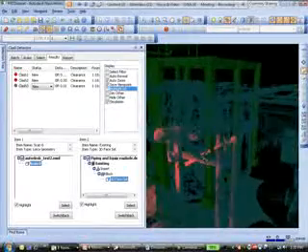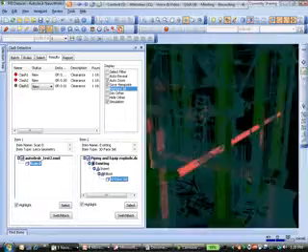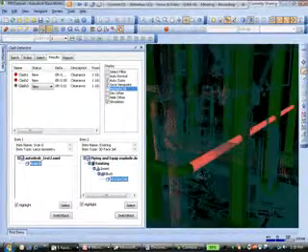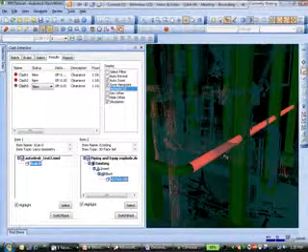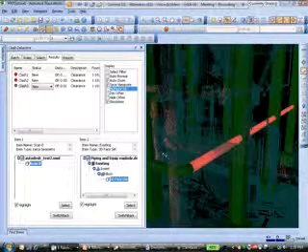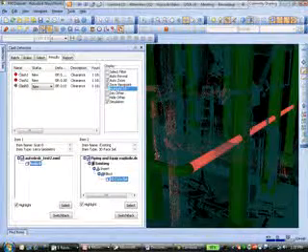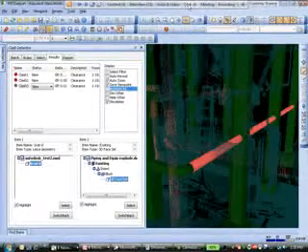There's also additional software out there that starts to take these point clouds and create a series of surfaces so that they almost behave like a 3D object. So right now we can see here's the potential conflict. We have this horizontal pipe, and it's impacting one of the existing pipes that are already in place there. So leveraging this information, we could go back and make necessary design changes, resubmit this model, and go through the clash detective again. So this is an example of bringing existing information in the form of a point cloud and then utilizing that against some new information inside of Navisworks.